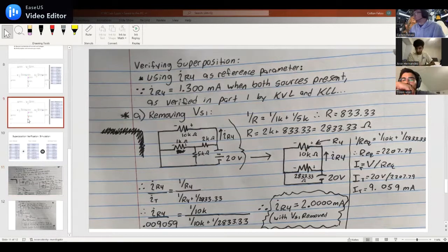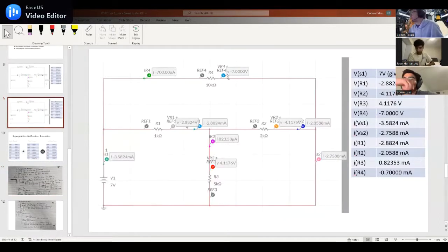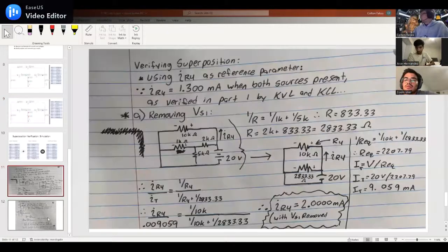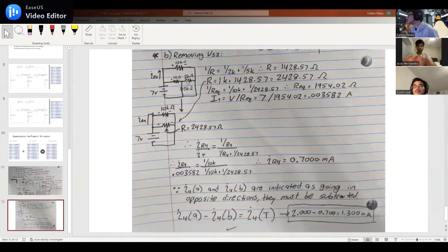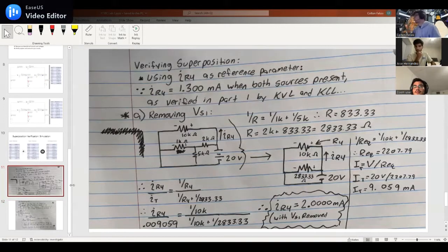I thought, if I was going to choose one element, the element that would make the most sense would be resistor 4, because it's kind of off on its own. So the best way to do that would be, I thought, a current split, because, right, guys, we want to make sure that we know exactly the amount of current going through that branch specifically. So if we don't have, for example, the 7-volt source there, we only have the 20-volt source, then we can go ahead and clean up all that stuff on the bottom, right? Once you get rid of one of the sources, and you can see it on the other side too, if you get rid of this source instead, then you have these two that are in parallel. You can create that as an equivalent resistance, then put it in series with your one here, which will bring you down to just those 2 in parallel. So you've got the 2 in parallel with just the 20-volt response and then the 7-volt response.